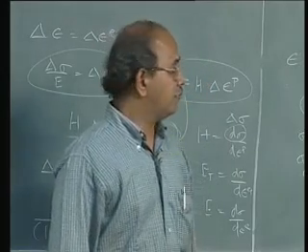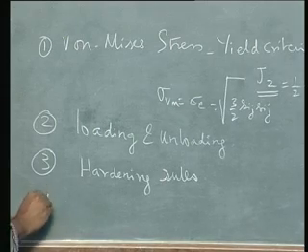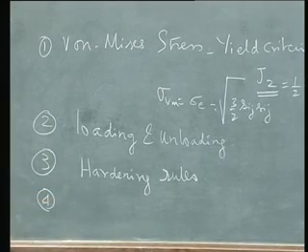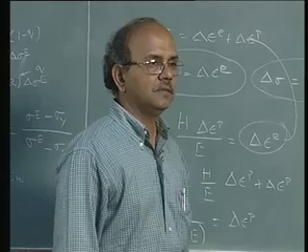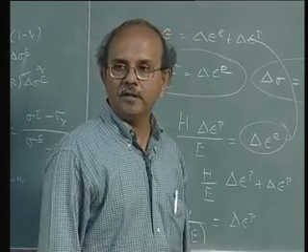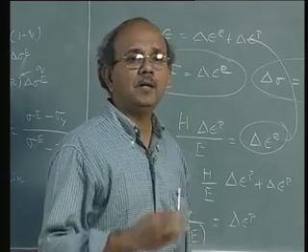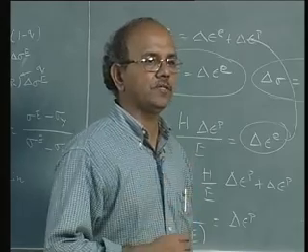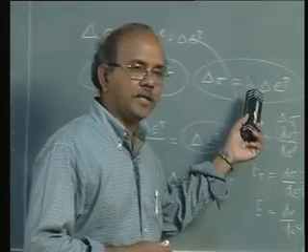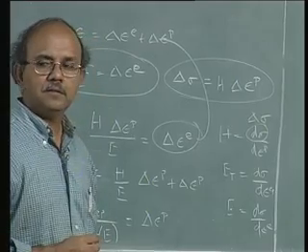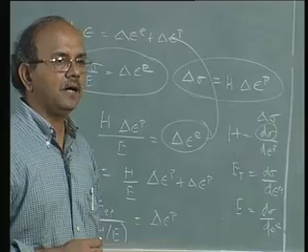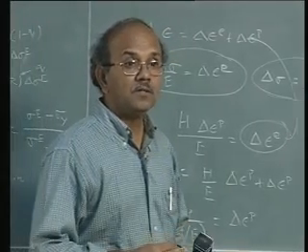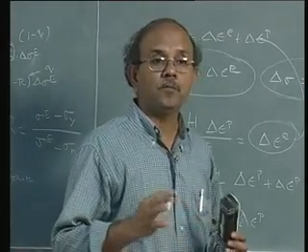And the fourth issue, that didn't figure to that extent in the one-dimensional case, is important for us to calculate the individual plastic strain components. Here I had a beautiful H, so I was able to calculate delta epsilon P, but in a multi-axial case I need a proper rule to calculate individual components of delta epsilon P.